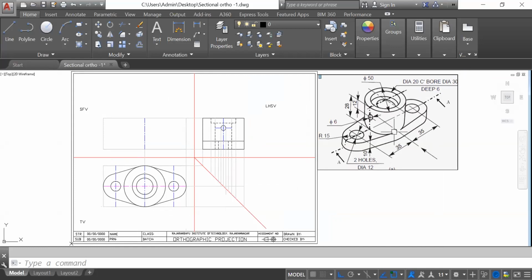Only the change would be in the sectional front view. Means the front view is a sectional type. So that's why we have to draw it considering the sectional. So we have to consider that the object is being cut from AA and this front portion is removed. So when we open it, how that view is visible, that we have to draw it here. Before cutting, this part is hidden. So it would look like this, whatever side view I have drawn.